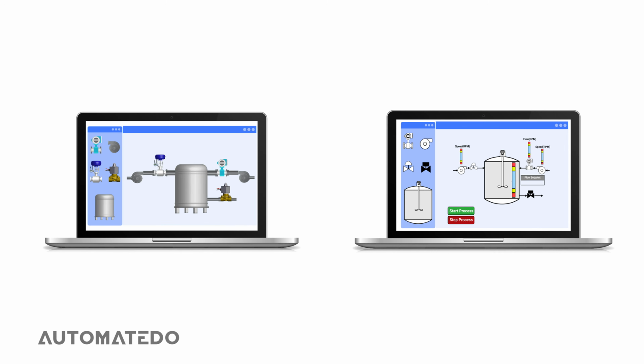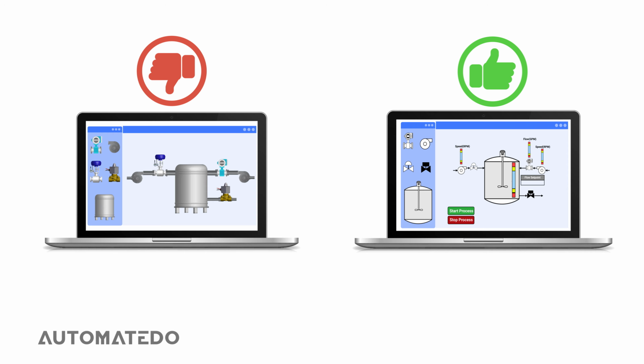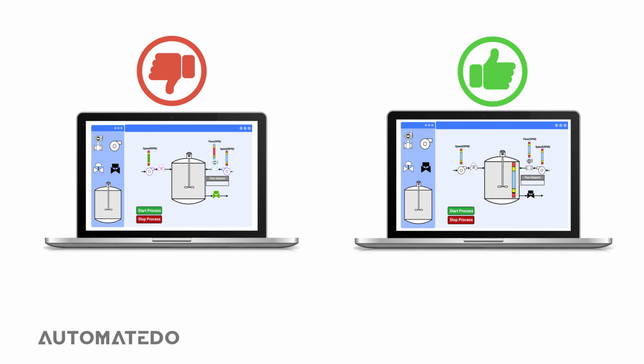Simplicity. Avoid crowding a screen and don't use improper 2D or 3D graphics which may interrupt the user's focus on important information. And consistency. The design flow should be consistent while retaining intimate details. For example, ensure that color codes are consistent throughout the system when displaying status information.